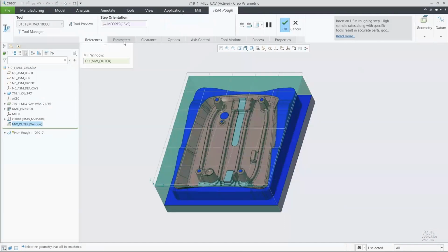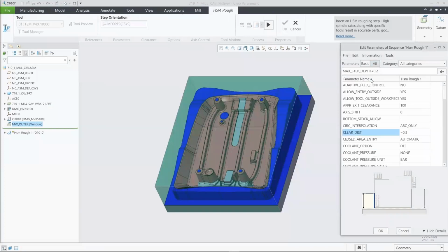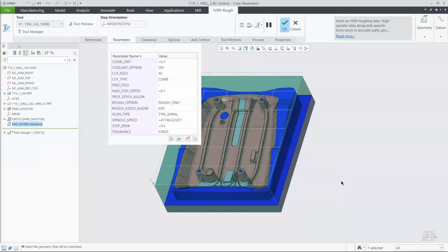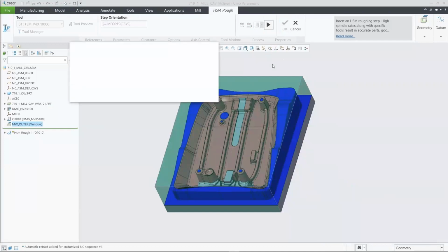So all you have to do is switch a parameter, set the different values for your feed rate. You can slow it down to as much as 10%, so we can see what it is right now. I'll go through all of those different options, change them to whatever we need to do. Once we have that adaptive feed rate set, we can change the minimum maybe down from 20 to 10, but otherwise maybe run it at a full rate. So now with those two different settings, the system will recalculate with our new adaptive feed rate.